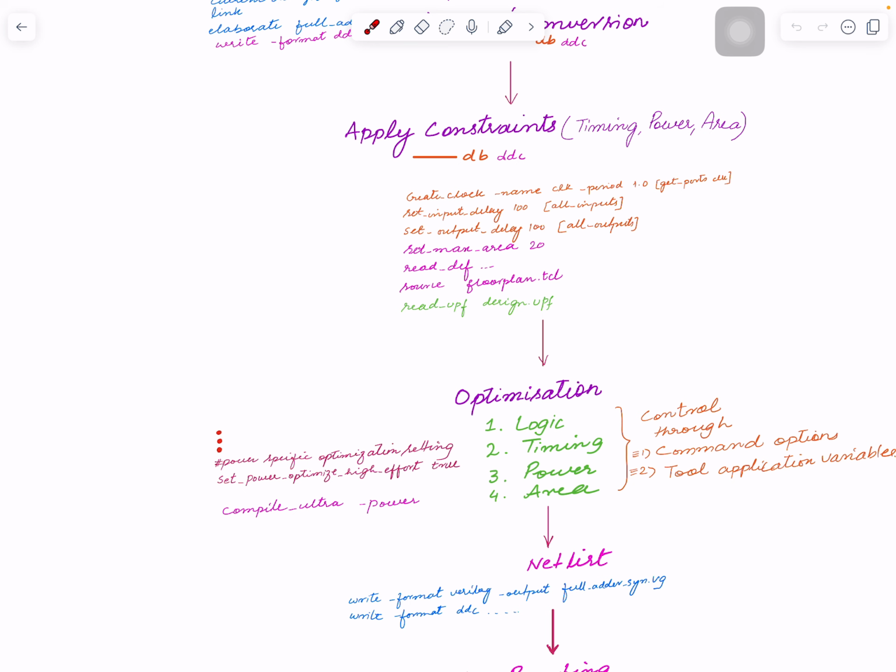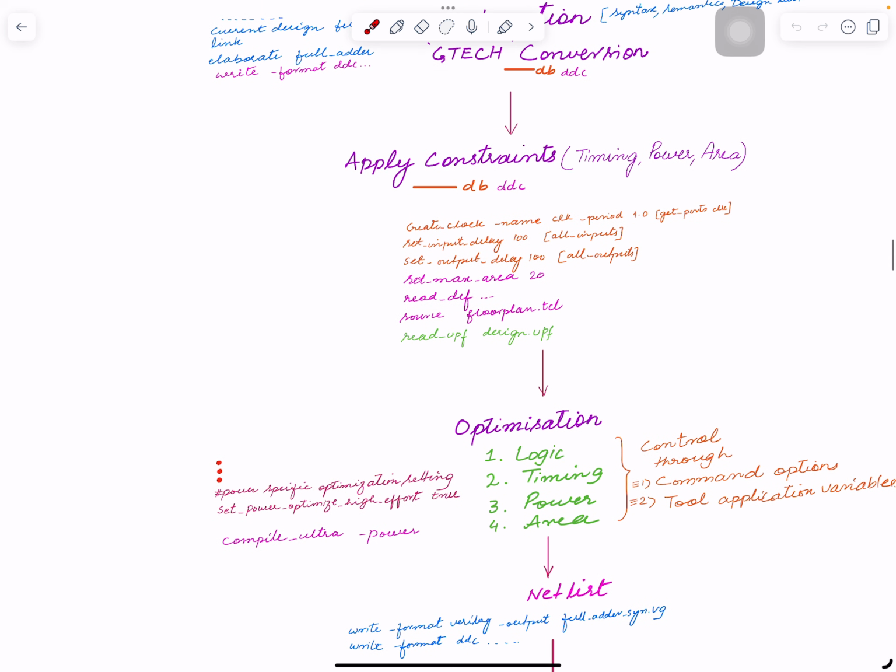Rarely does it happen that you push a button, have all these files in a Tcl file, just source that file, and all these stages are done. It rarely happens that what you execute the very first time gives perfect QoR. That doesn't happen. So it's a lot of iterative updates, analysis, and all that. All those people who think physical design is push button, it is not. Maybe for a simple design it is, but that's where you can tell the difference between a good and a not so good physical design engineer. A good physical design engineer needs to know how to control the tool to do the maximum possible optimization in order to meet the timing constraints that you provided. Sometimes an overly aggressive constraint might do a bad job, so it's a balance that is needed.